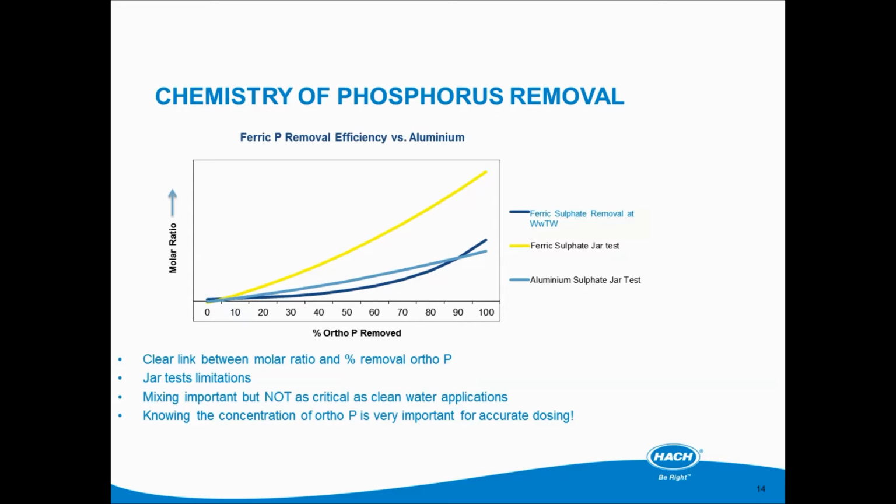The two main metals used in phosphorus removal are aluminium and iron, for both precipitation of phosphorus in the primary settling tank and also dosing after the ASP for precipitation in the final settling tanks of an activated sludge plant. Until recently, the dose of the metal salt has been based on the results of jar tests alone.